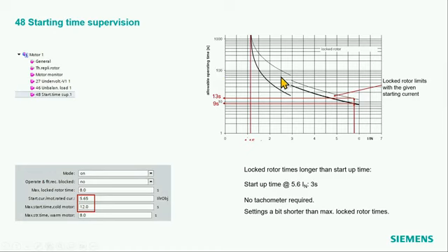It's equivalent here because this curve follows, let's say, the calculation formula I gave you beforehand. So what I did here, instead of 13 seconds, I put 12 seconds. Instead of 9, I put 8 seconds here. So I'm a little bit shorter than the maximum locked rotor time, entering here my maximum startup current time here. And of course, the startup current as such, 5.65 times nominal current, is what I put in here.